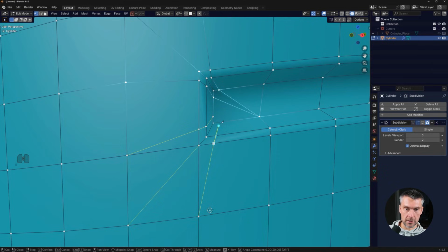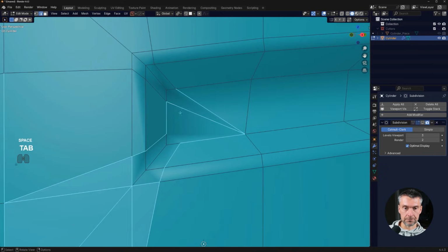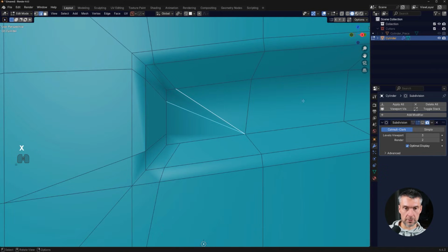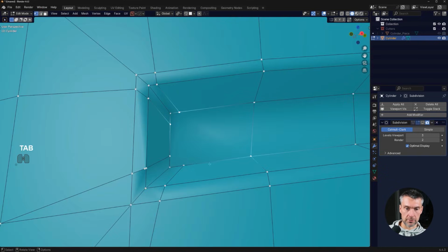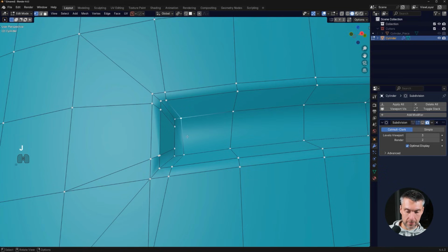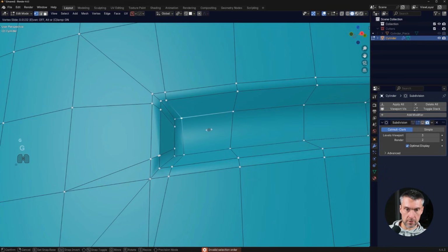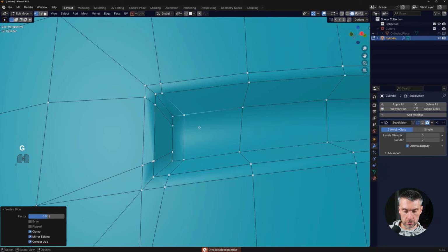And this is why you need denser subdivision initially, right? So you need denser mesh on this element, because anytime you cut smaller elements in the mesh and you're running a sub D on it, you need to make sure that you have enough topology to do that, okay? So I'm gonna run it like this here, right?